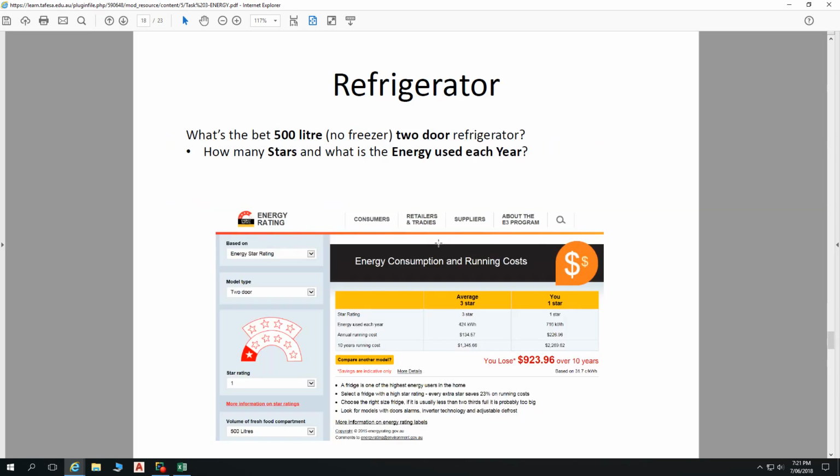But it gets confusing because you think, oh, hang on, that's given in the description anyhow. So that's still going to get to that 125,000 lumens, isn't it? Yes, exactly, with that 60 watts, or whatever lumens it is you determine. It has to be produced for that office space.